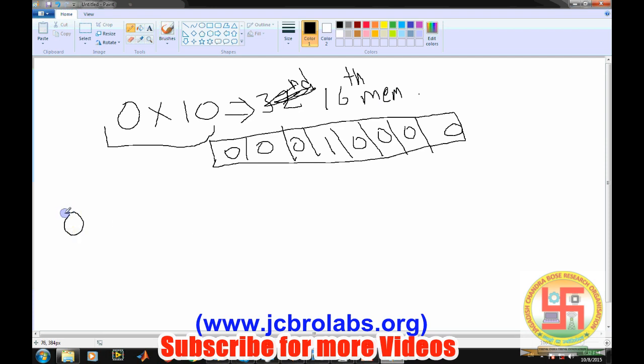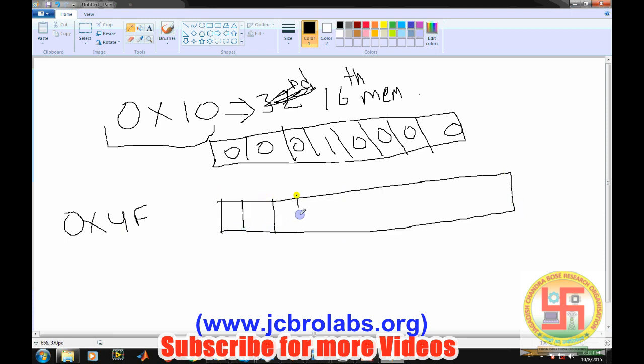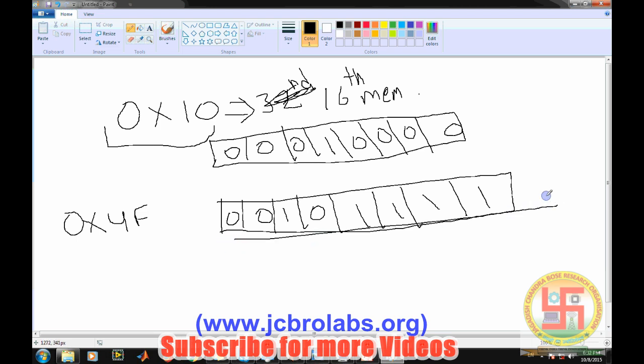Similarly, if we are providing 0x4f, you can also find which particular memory location we are accessing. In binary it is 0 1 0 0 1 1 1 1. You can convert this binary number into decimal, and from that decimal number you can find which particular memory location we are addressing. Ultimately in hardware the data propagates in binary form, but hexadecimal is just for the sake of representation, to be understood by human beings.